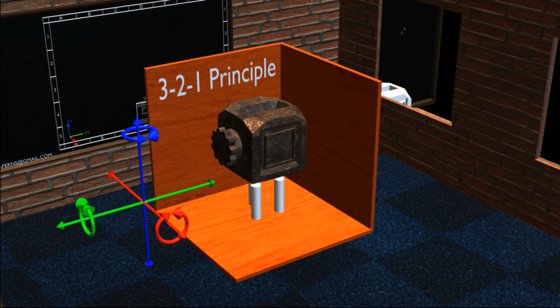So with this, we can get rid of translational motion along the z-axis, and rotational motion about the x-axis and y-axis. Hence we have constrained the z translational motion, x rotational motion, and y rotational motion.